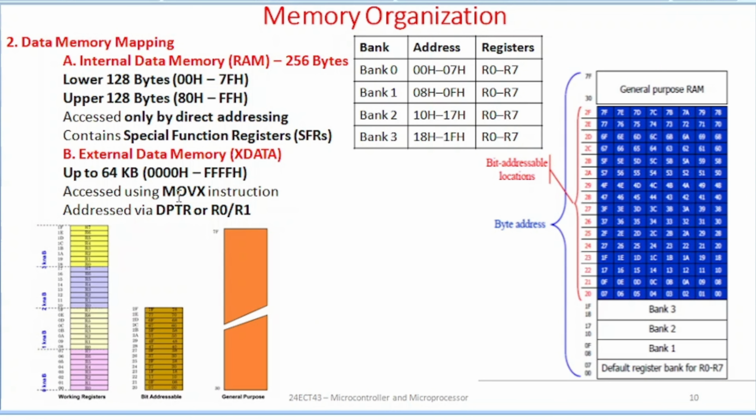The total internal data memory is divided into three blocks: lower 128 bytes, higher 128 bytes, and special function register space. The higher memory is again shared with the special function registers for ports, status control bits, timers, registers, stack pointers, and accumulator.